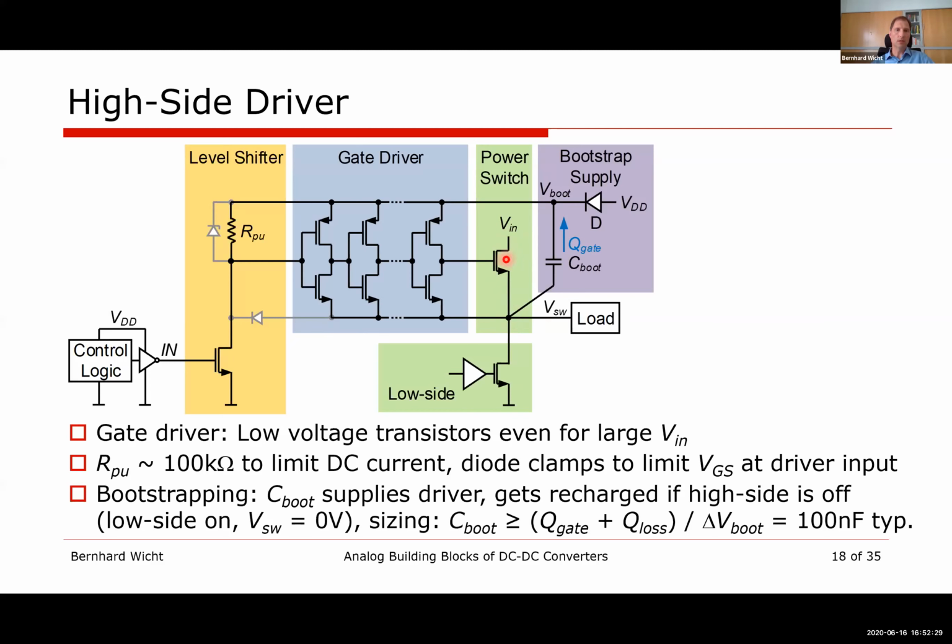The other point is the instability that you're mentioning. That can quite easily happen: your control loop components, your sensing circuits, may get triggered. That's why a very simple approach is, in the very first moment when you have your switching, you simply blank and mask your sensing circuits so that they wait until the ringing decays, and then we do the sensing.